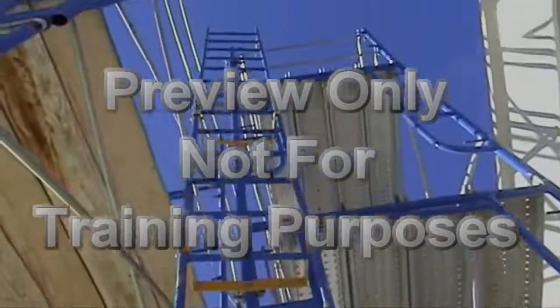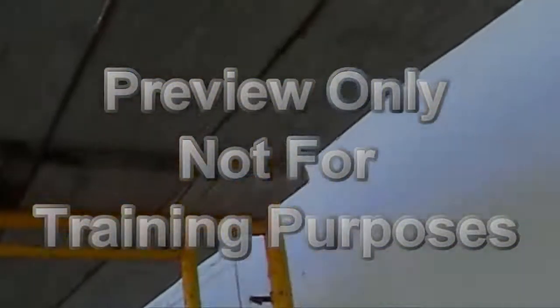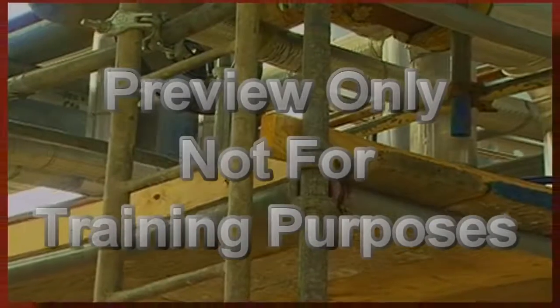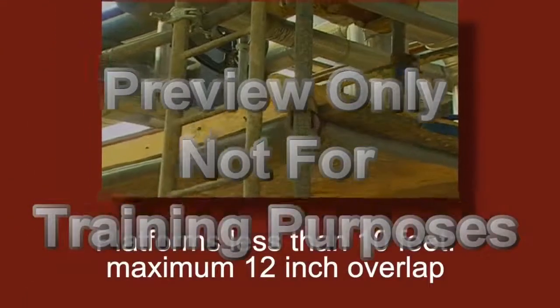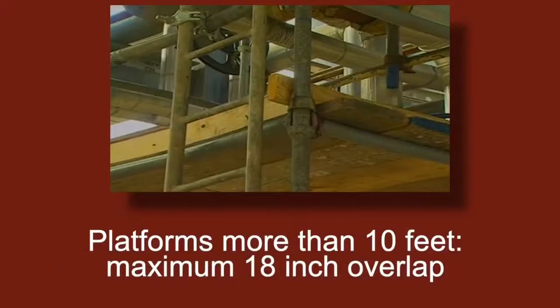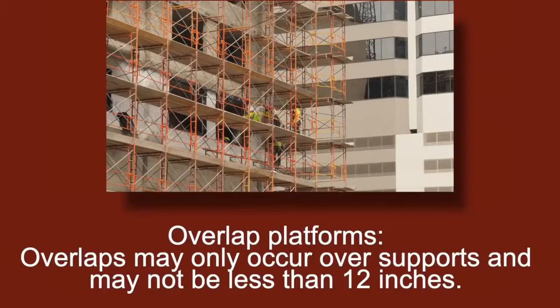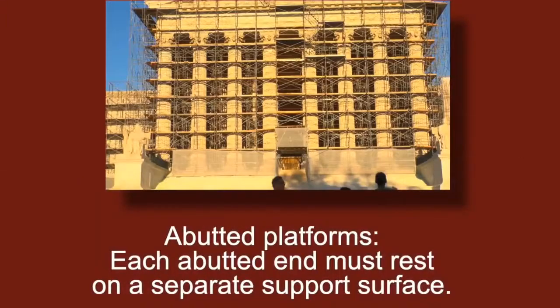To prevent slippage, platforms must be cleated or restrained at each end or overlap centerline support by at least 6 inches. Generally, each end of a platform may not extend over its support more than 12 inches for platforms which are 10 feet or shorter in length, or more than 18 inches for platforms which are more than 10 feet long. On scaffolds where platforms are overlapped to create a long platform, the overlap may only occur over supports and may not be less than 12 inches unless the platforms are restrained to prevent movement. On scaffolds where platforms are abutted to create a long platform, each abutted end must rest on a separate support surface.